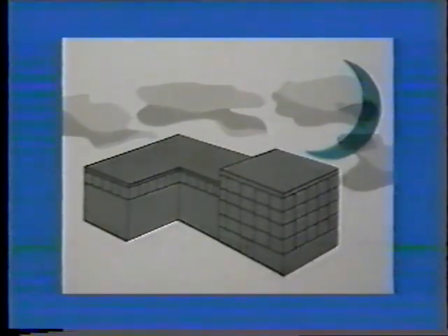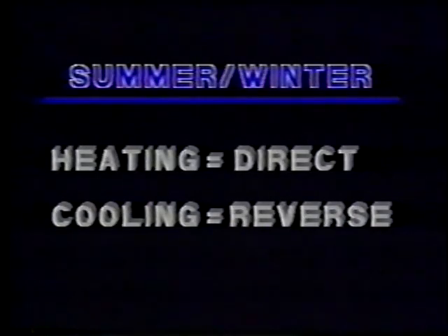Dual pressure thermostats fall into 2 categories, day-night and the summer-winter models. In a heating application, the day-night thermostat provides the ability to have night setback or temperature reduction during those times when the space is not occupied. This function is performed automatically by changing or indexing the main air pressure to the thermostat either upwards or downwards. The summer-winter thermostat provides changeover from heating to cooling or direct to reverse action by a change in the main air supply pressure. Let's discuss single pressure thermostats first, since they are more commonly found in the field.